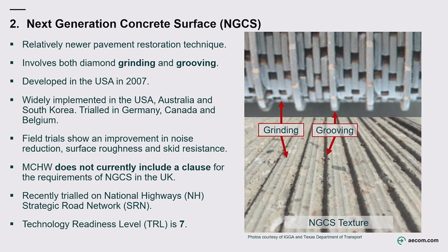We've seen from field trials that there are some improvements in noise reduction and in skid resistance. Currently, MCHW does not include a clause for NGCS, and we hope by the end of this project we will be able to develop one for them.